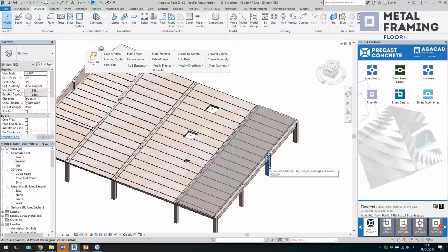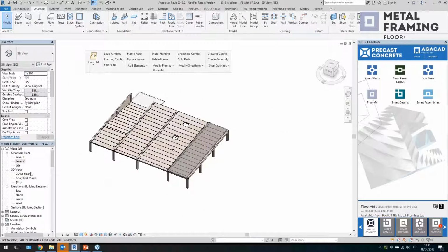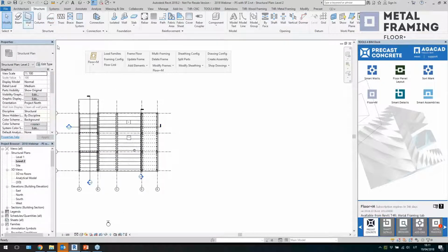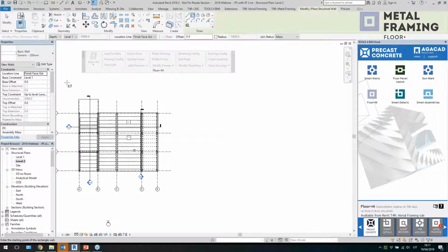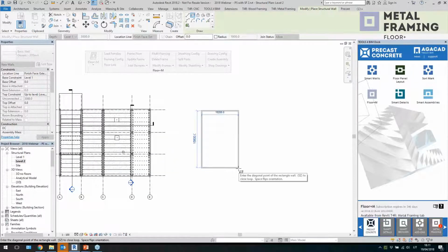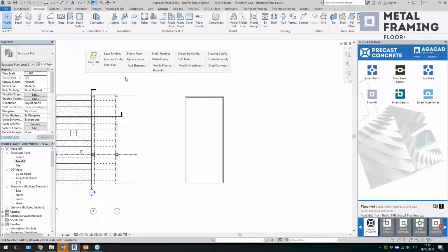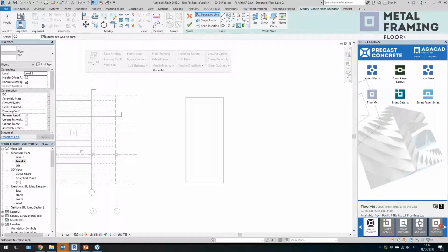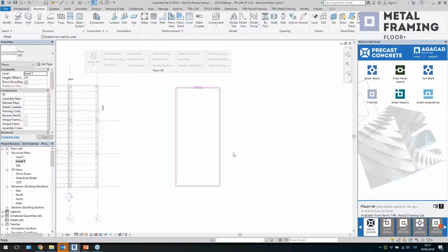Okay, what else? Just a couple of other examples. I will go here, and this time I will draw a couple of walls also. Let's say wall, select the type of wall, the depth, and then I'll just draw it. Let's say what should be the length of my walls. Okay, let's do it like this. Then create another floor. Just select one from the list, and I will use this command to attach my floor to the walls. Okay, make it like this.